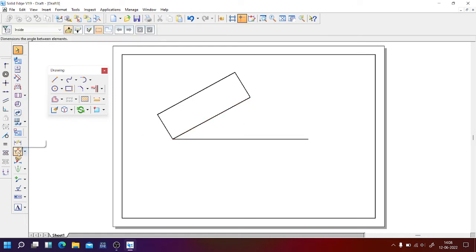So rotation will take place stepwise. You need to take care. Okay, it is rotated 30 degrees. This is what rotate does. Suppose you want to create multiple objects by rotation in steps, then you turn on the copy option. So now let us observe here. I'm going to do the rotate with the copy option here.